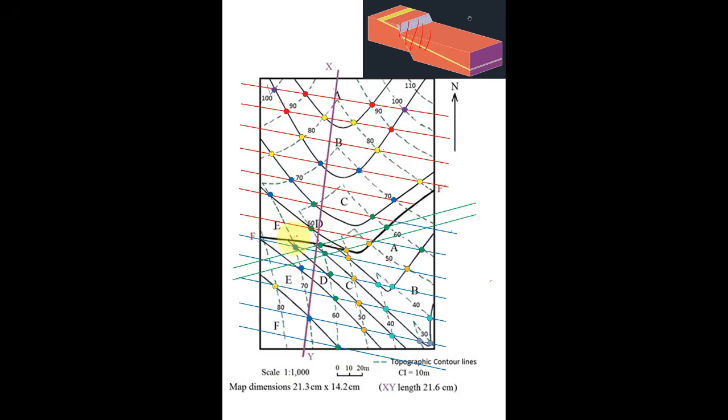Then we have this 70 on both the sides. Then do we have anything else? 80 we have. Yes, see this 80 is there and it goes all the way like this, and here again 80 is there, right? So we'll pass a strike line. So you can see that the spacing of these strike lines are definitely different, which indicates that the inclination of the fault is different from the inclination of the rocks.